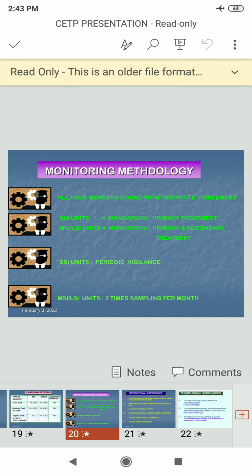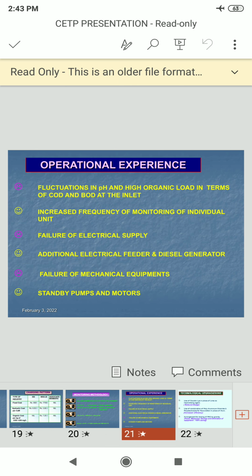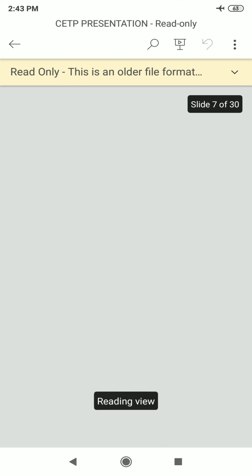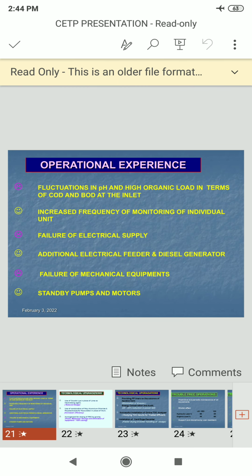You can see there is a methodology for monitoring the clarification of the effluent treatment, and the basic effluent treatment plant is most important. Stepwise treatment of industrial effluents plays an important role. That is solid removal. Most solids can be removed using simple sedimentation techniques. With solids required as slurry or slush, very fine solids and solids with densities close to the density of water pose special problems.